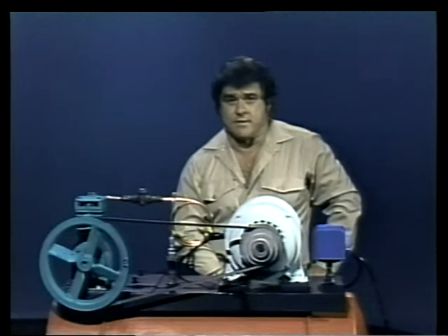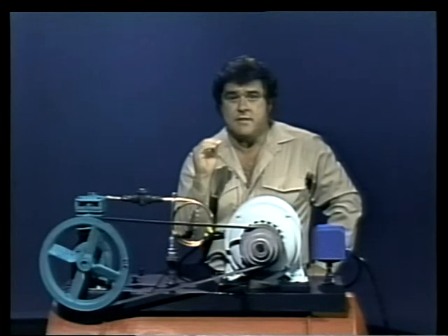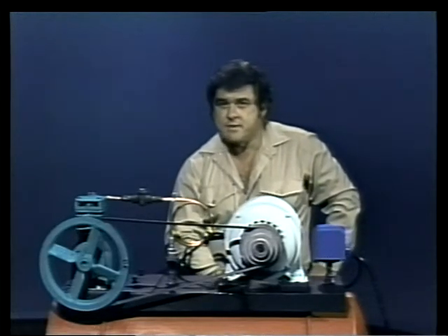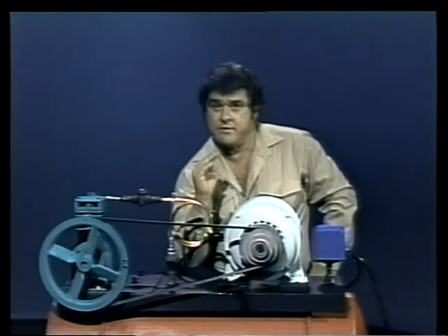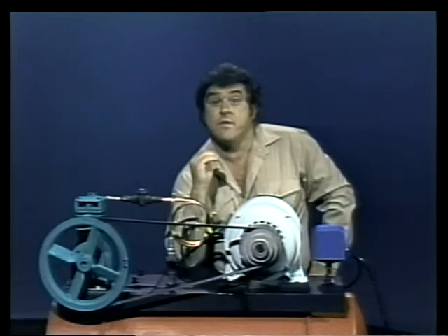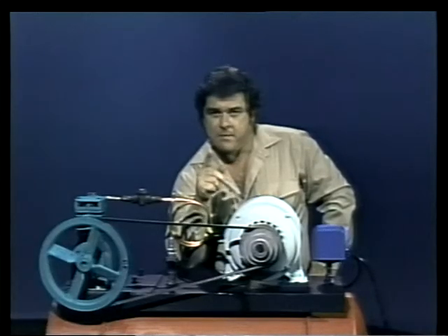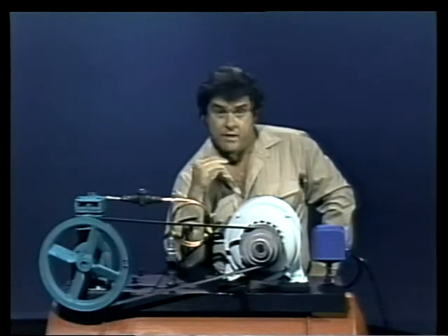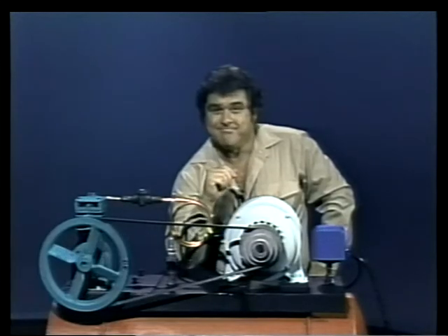The liquid ring compressor, like all other positive displacement types we've seen so far, compresses by trapping air in an enclosed space and reducing the volume of that space. The next type of positive displacement compressor we'll discuss, the rotary blower, works a little differently. It does trap a quantity of air and squeezes it together, but it does it without reducing the volume of the space. Instead, it packs more and more air into the space, in effect, using more air to squeeze the air that's already enclosed. Let's take a look inside a rotary blower, and you'll see what I mean.